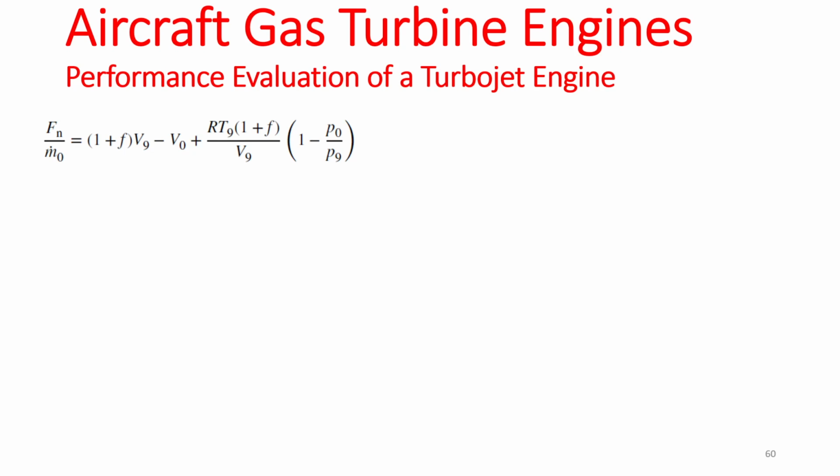Exactly. Thank you. That was a very good out of the box thinking. Exactly. So we know that the speed of sound at station 9 is the square root of gamma RT9, right? So essentially RT9 is going to be equal to A9 squared divided by gamma. You plug that in the equation you have here, right?